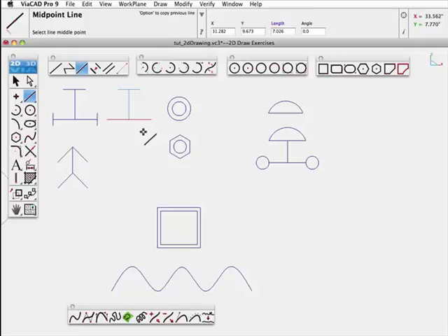As you create, you'll look at the circumstances and pick the tool that makes it easiest to achieve the results. And the midpoint line tool makes this much easier. And we'll use the same tool to create the ends. In fact, after the first is drawn, by pressing the Control key, you can click a single point and a duplicate of what you just drew will be placed. Notice we used the midpoint line tool, so the point that you picked was the midpoint designating that next copied version.